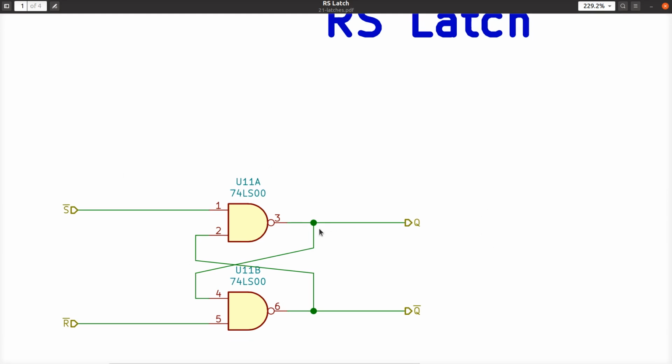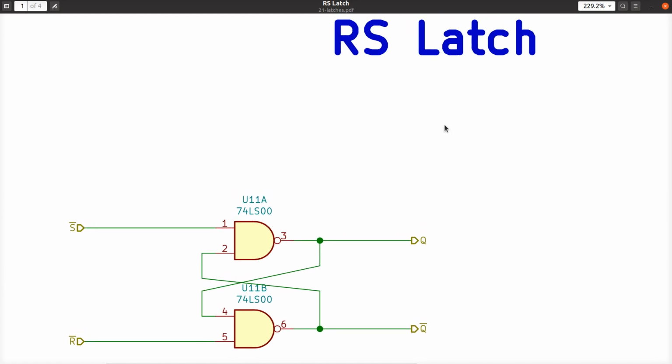Anyway, let's call this a latch. Some people call it a flip-flop, and the word flip-flop has to do with the fact that these things flip and flop their values back and forth, all right? The word latch, on the other hand, represents that the output here latches onto the input. As you can see, that's what's happening here, right? The memory latches onto history in some way and can tell you what has happened prior to the current point in time. Provided, mind you, that you didn't do something you're not supposed to do, like set both of these to 0 at the same time.